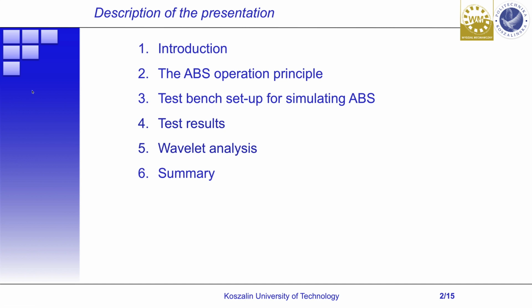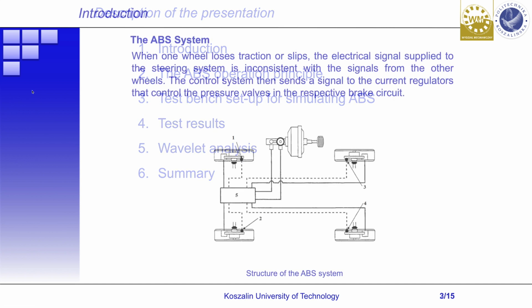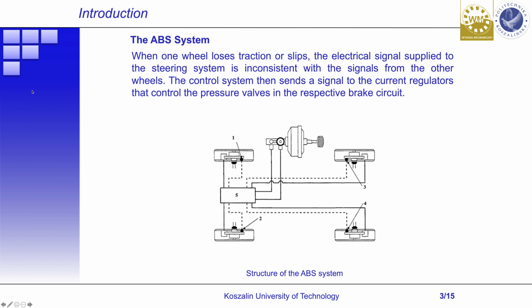The ABS system shown in the figure, which prevents loss of wheel traction, consists of two systems: hydraulic, valves regulating brake fluid pressure, and electronic, wheel speed sensors. The voltage generated during the measurement of the rotational speed of the wheel, which is generated by induction sensors, items 1-4 in the figure, located at the toothed rim attached to the wheel axis, is amplified and then transmitted to the control system, item 5 in the figure, where the speed of all wheels of the car is calculated.